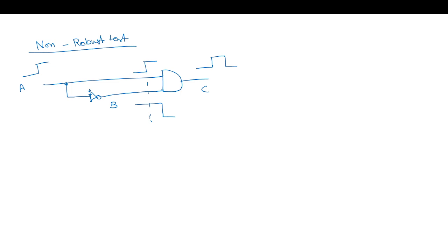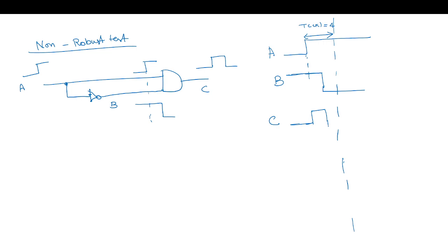Now, if we have an A like this, at this point we are capturing. This is the A. The B, instead of transitioning here, takes some time and then goes to 0. Now see this transition time, it will go to 1 and 0. So in this capture phase, where it is capturing, it is 0, so it's a correct value.